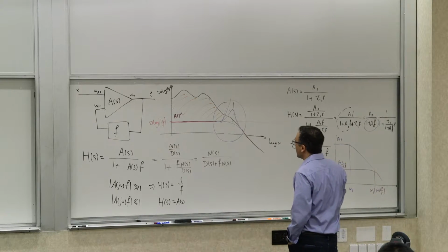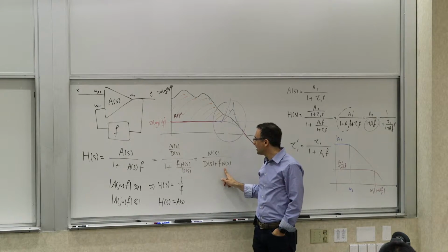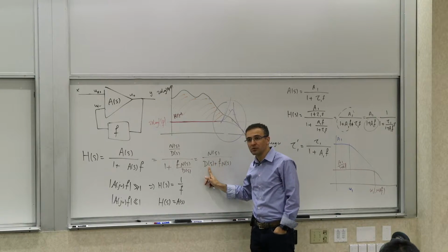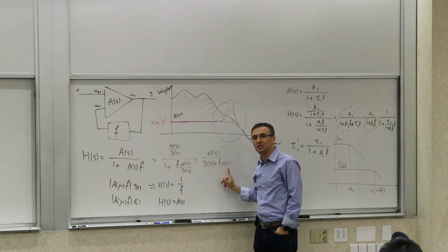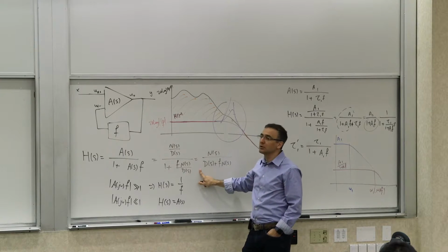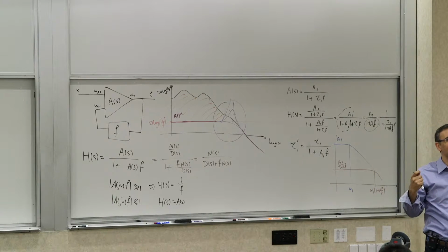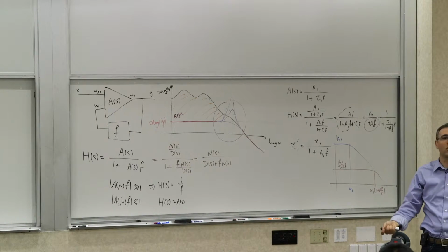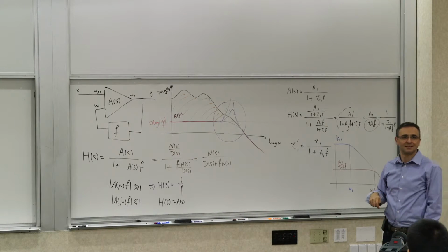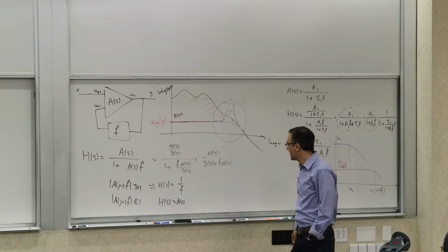But the poles have moved. So when you apply feedback, the poles start moving. And how much they move is a function of the feedback, but the location of the pole not only depends on the original poles and the feedback, it also depends on the zeros of the original transfer function. So the zeros of this forward path will have an impact on how the poles of the closed loop system move. And this is important. You can't say, well, the zeros don't matter. They do, because it's the aggregate response that determines that.